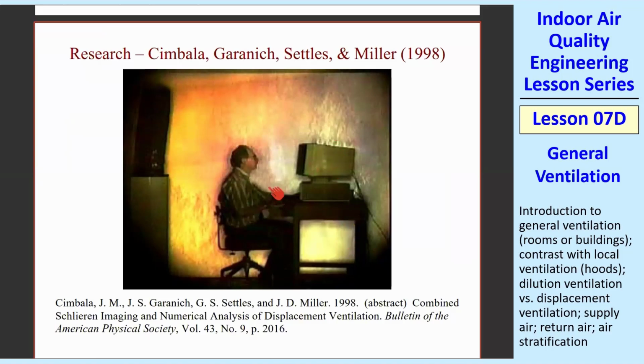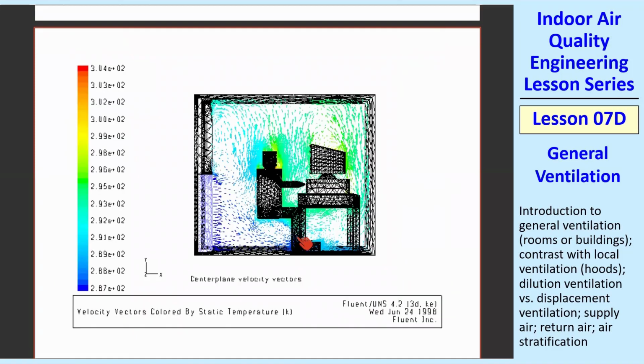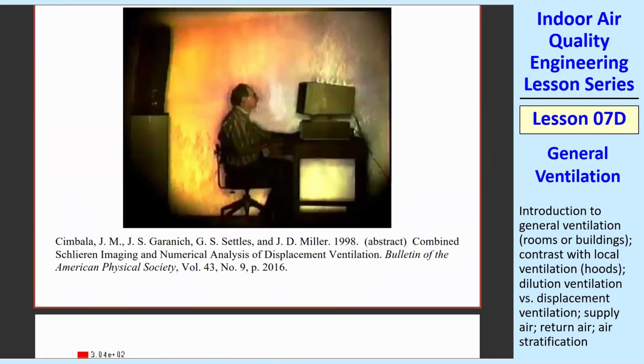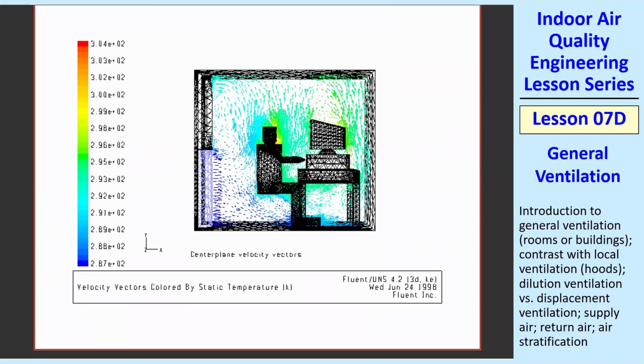You can see the thermal plume coming off, not so much the person, but the computer. That plume rises. What I did was some CFD, some computational fluid dynamics of that same thing, just with a Tin Man kind of figure and a computer. So we tried to imitate this picture, and you can see that we're capturing this thermal plume pretty well. And so that was a successful application.